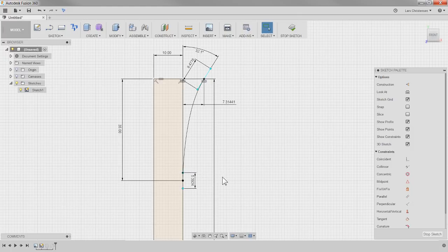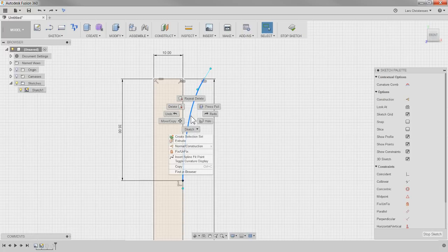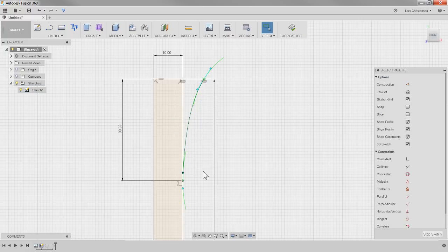I normally would say put the dimensions on that you kind of want. I'm just doing Control Z to undo all these dimensions. When you get it to a point where you would like it, I think it's okay to right click on the spline and fix it. Now, I don't think it's okay to fix anything other than splines when it comes to sketch geometry. It turns green, but tells me that it's fixed. I can't move it around right now. And so I think that is okay.